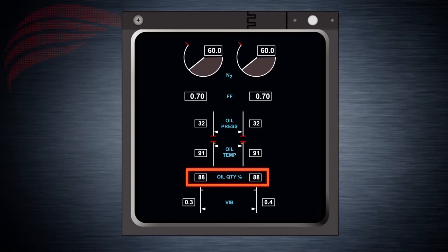When the oil quantity is 18 liters or higher, a full quantity indication is provided in the display units. A low quantity message appears when oil quantity decreases below 4 liters during at least 35 seconds. Also, the related quantity indicator's color inverts to alert the pilots of the oil shortage.